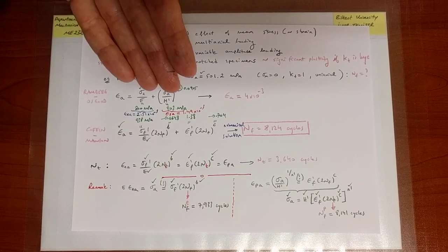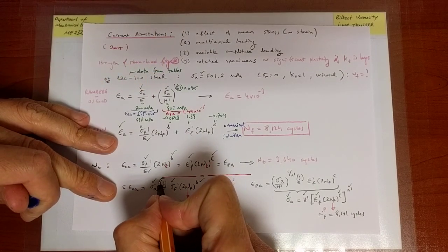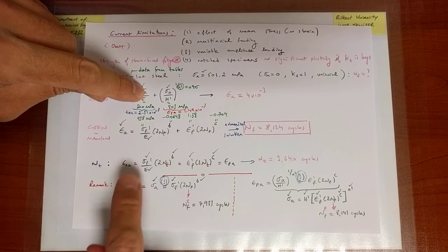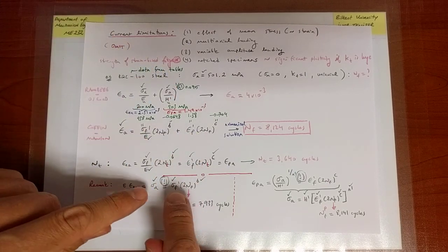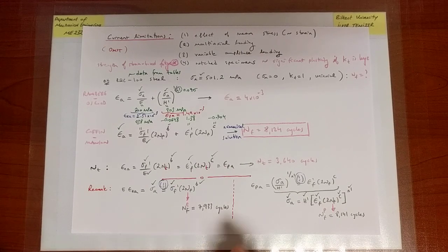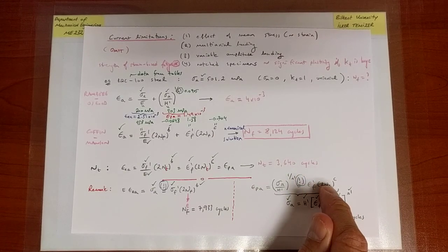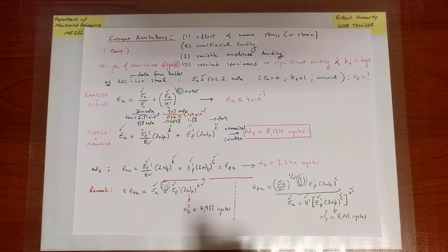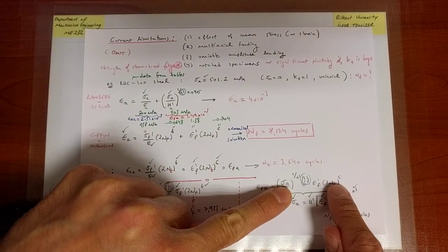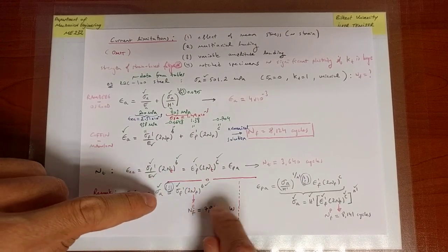Now notice that when I'm invoking these parts of the argument, so let's put them in blue, these exclamation marks are important because we're saying that the elastic portion is either this or that, or either this or that. In other words, the left and right hand sides of these equations have to be consistent with each other, which suggests that the constants that we provide here are somehow such that that consistency holds. If I give you a number of cycles, if I give you a stress amplitude that is associated with failure based on the stress amplitude, let's say I give you 501 and 8,124, you plug them in here, it has to hold. It doesn't, it won't, because for it to hold, NF should be not that, but this, okay? And in this case, NF should be not this, not that, but this.